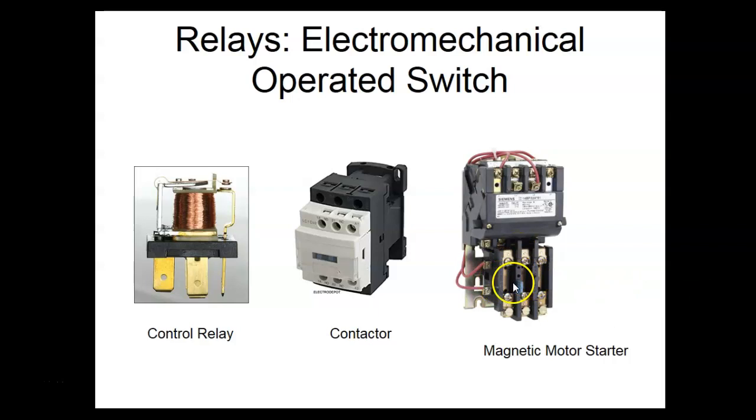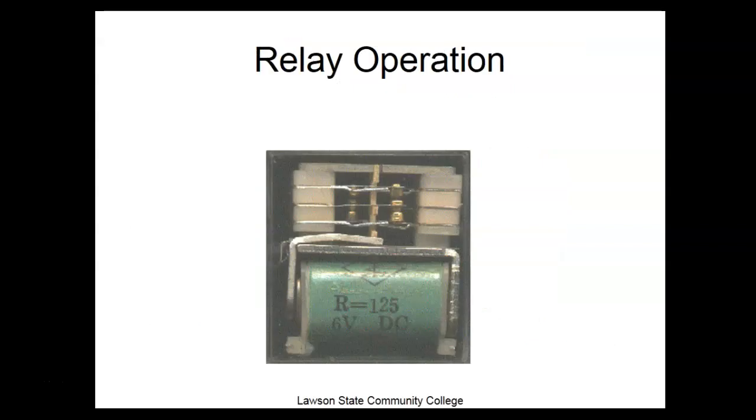Motor starters have sensors on them. The circuit breaker or the fuses allow the motor to start, and then we have a sensor on it so that if the motor stalls, we can disconnect the motor without popping the breaker. We'll look at some motor starters. We've got motor starters on the Amatrol line, which have overloads, and we can show you that.